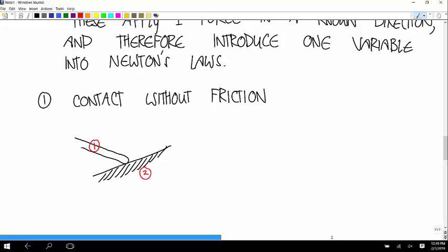So what's the direction of the load? What load does this joint apply? We've already seen what it is before. Yeah, it applies a normal force. It applies a force perpendicular to that surface that prevents this from moving into the surface. If this thing tries to sink into the surface, the ground fights against it to keep it from doing that. You follow what I'm saying about how it comes from the restrictions that the joint makes that determine what loads are applied?